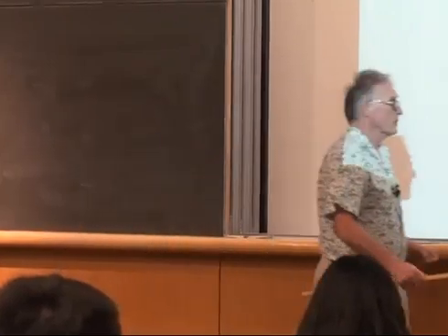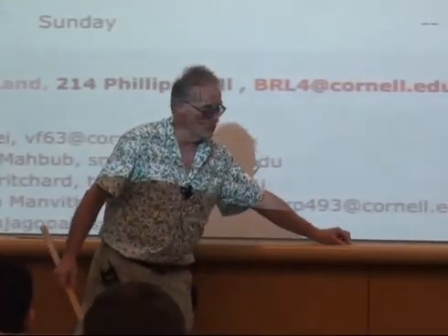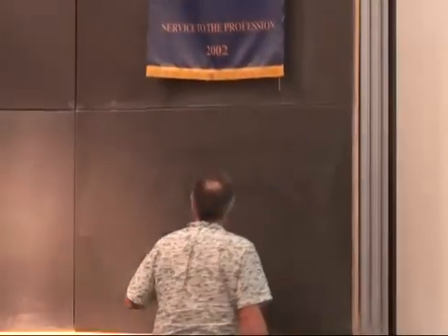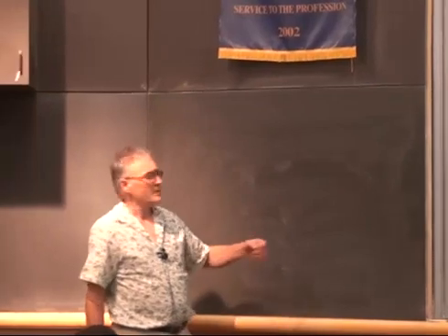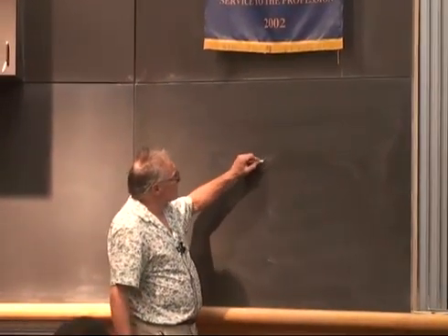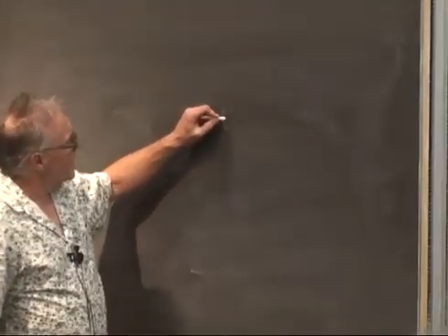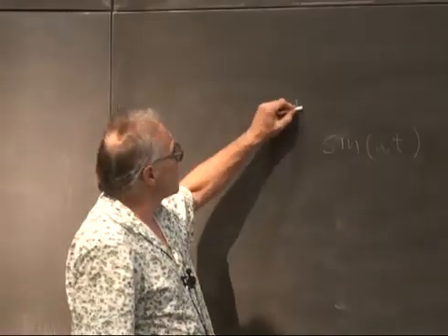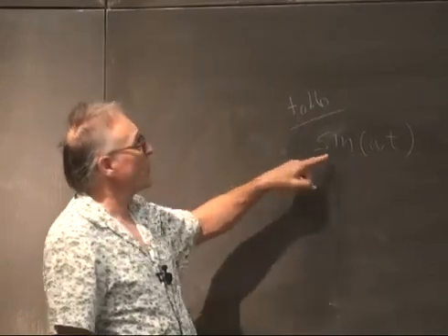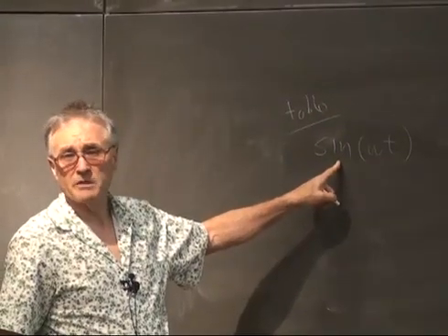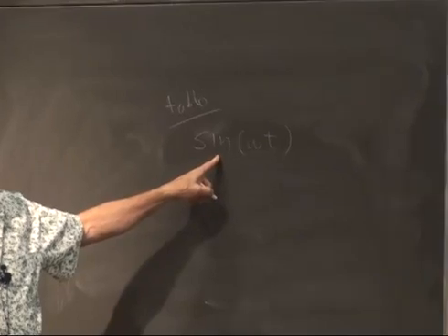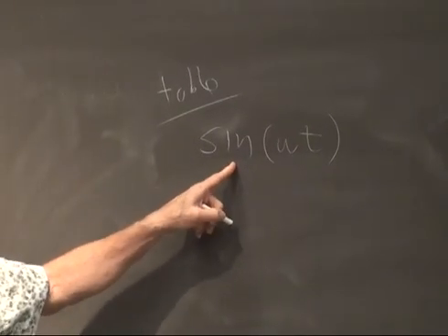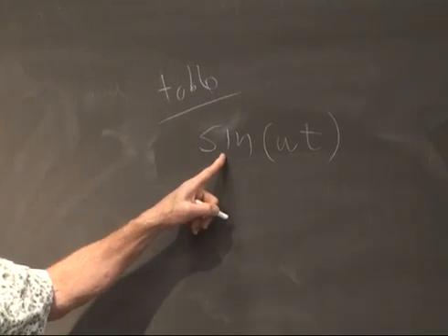Sure. So the question was talking about ramping the amplitude up. The mechanics of it is that you're going to do the table lookup and you're going to get sine omega t out of the table lookup, right? You can't afford to do this sine operation, which is a floating point operation, in real time, but you can afford to do the table lookup from the interrupt service routine. So you're going to do the table lookup to get this value.